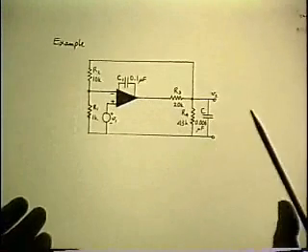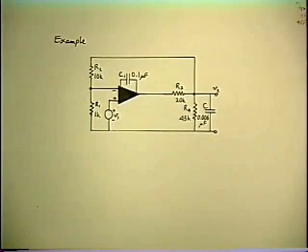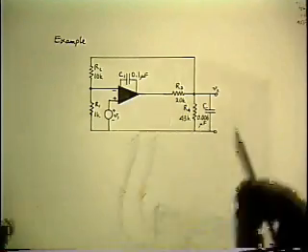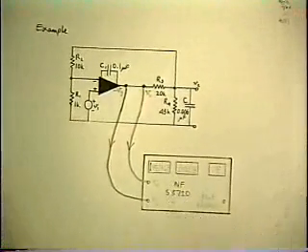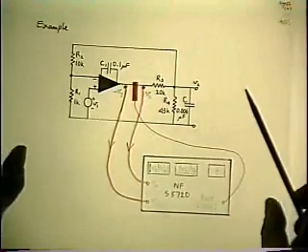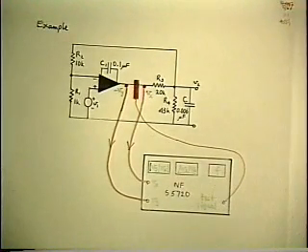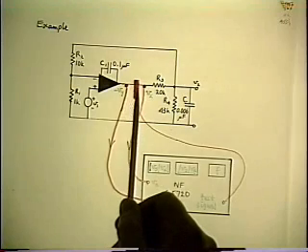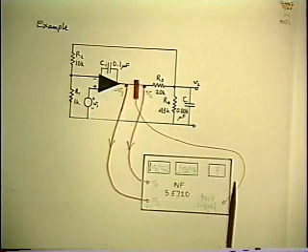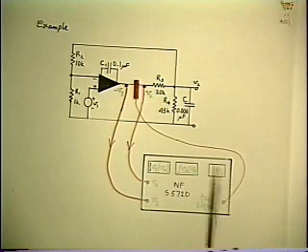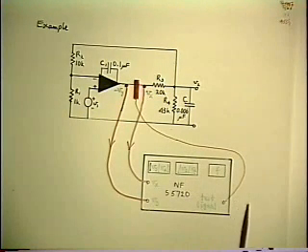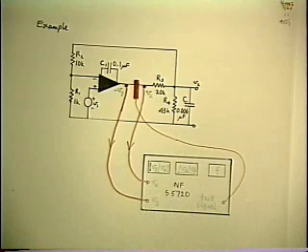However, it turns out you do have an isolation injection transformer handy all the time. And it's called an AC clip-on current probe. And that's all it is. It's a transformer, except normally you're supposed to use it to measure a current. What you do is clip it around a wire whose current you want to measure, and you put the other end of it into a termination or an amplifier, which converts the measured current into a corresponding voltage, and you can then read that on a voltmeter or an analyzer or whatever you like.